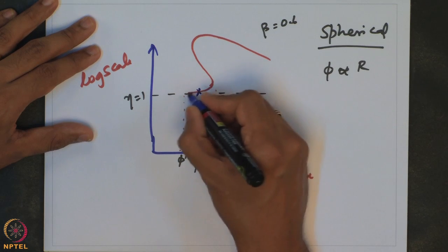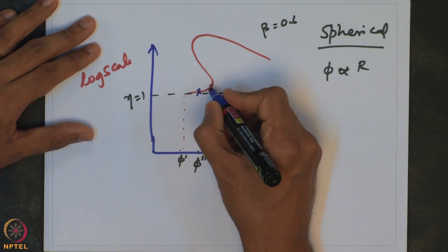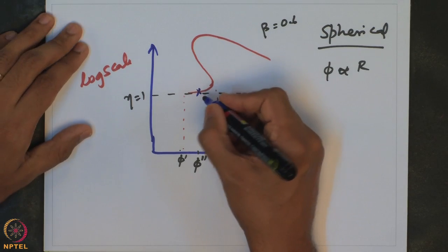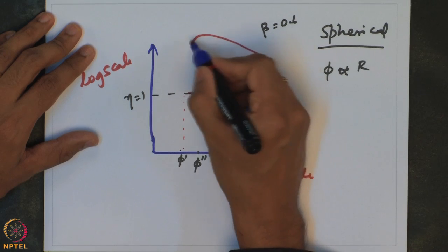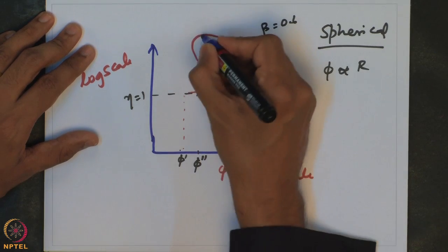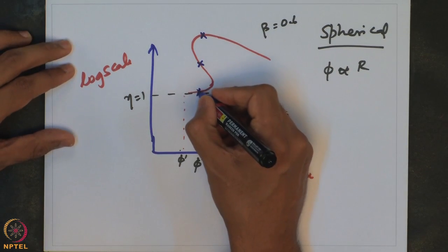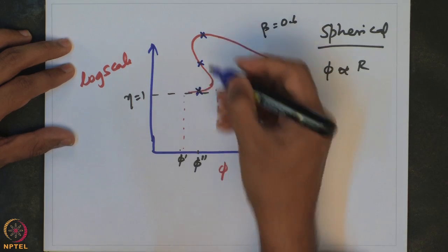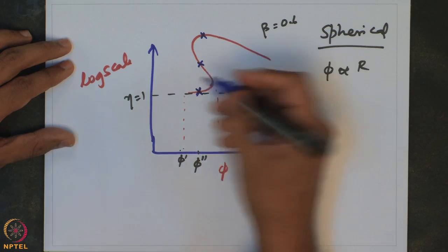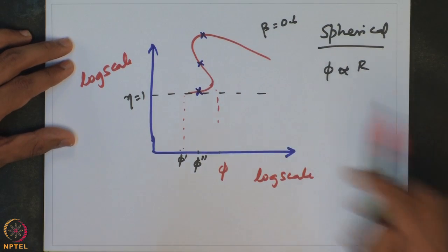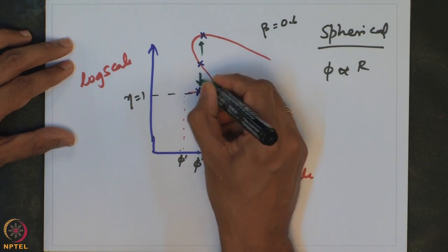And so, now if I operate at different values of phi, depending upon the initial conditions I choose for starting the reactor, the steady state may be present in this location, or the steady state may be present in the other steady state. So, remember that there are 3 steady states here. So, depending upon how I start the reactor and reach a steady state, the reactor might operate at this steady state or this steady state. It turns out that the middle steady state is actually unstable, and even if I start here, I would essentially land either into this steady state or into this steady state.